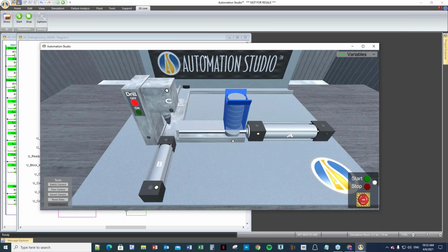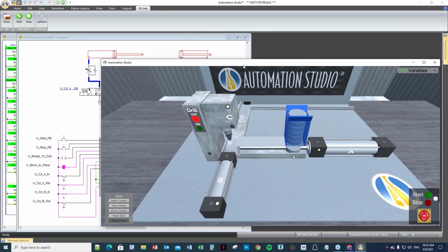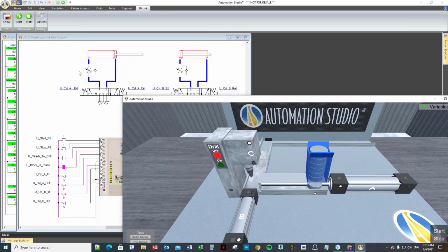So to really improve on that, you have to improve on the design of the pneumatic system. What we need to do is move here a little bit slower, adjust the flow rates by doing adjustment over here to make these things maybe go a little bit smoother.